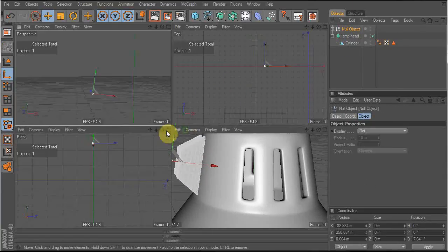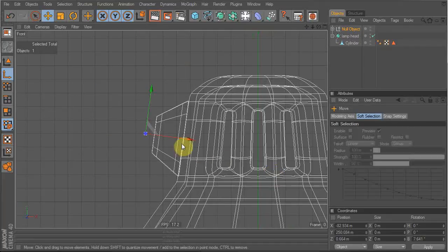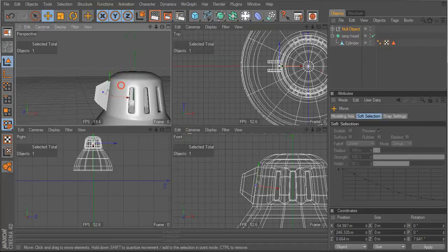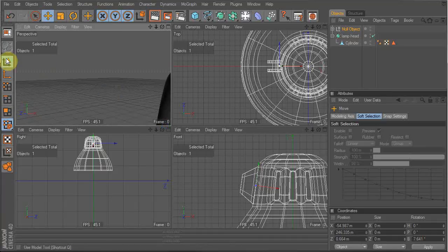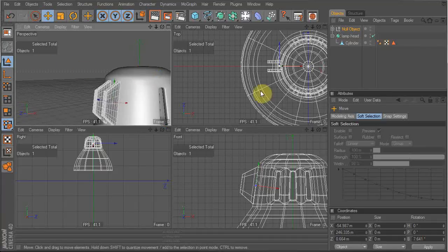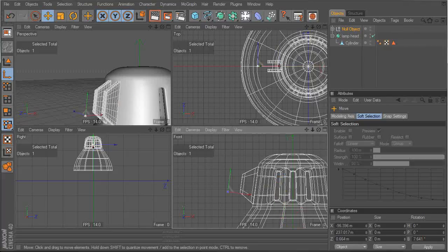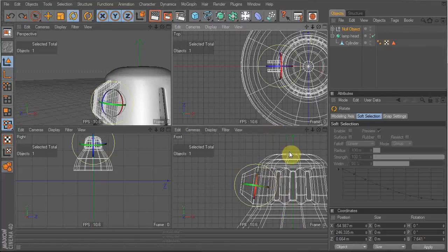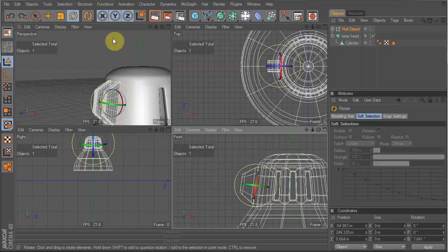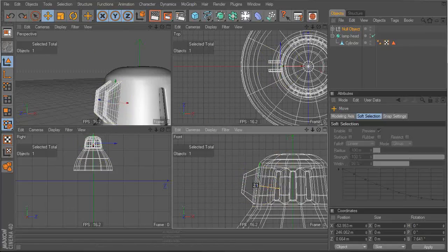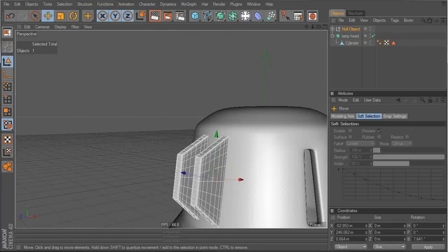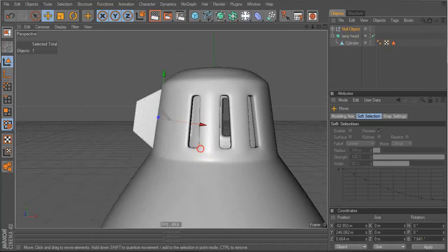And see, the axis right now is not in a very convenient place. We're going to move it right here, and then go back into here and change back to the model. By the way, that's how you move the axis. Sorry, I didn't explain that. You press this second button here, and now you can move the axis without moving the objects inside it. So, for example, we'll be able to rotate it around this place if we ever need to, and the same thing with movement. I'll explain this when I come to rigging. It is more relevant in that section.